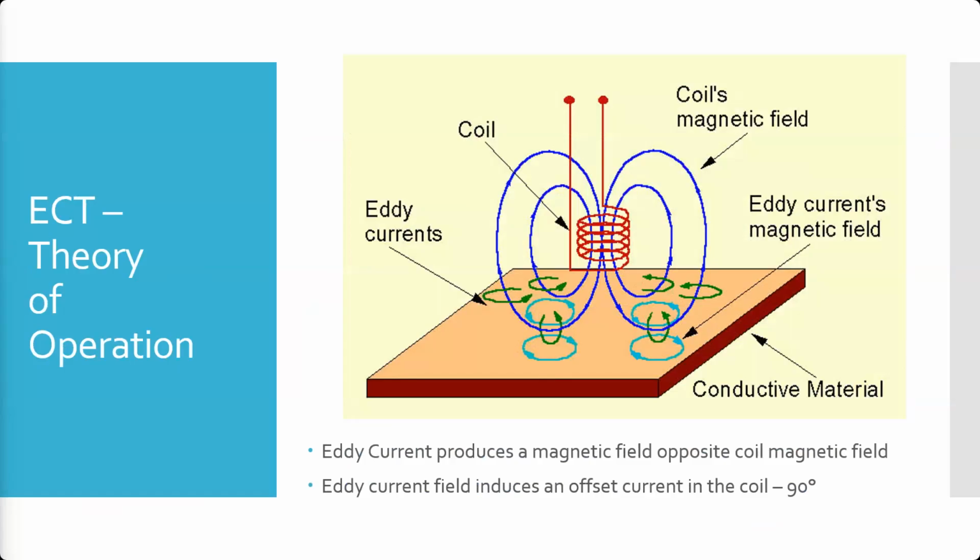And all three of those coils, even if they have the same diameter wire, the same length of wire, the same number of turns, are each going to have a different impedance or resistance, based on the fact that they have different materials near the coil or in the core of the coil. And the same thing's going to happen when we put that here.